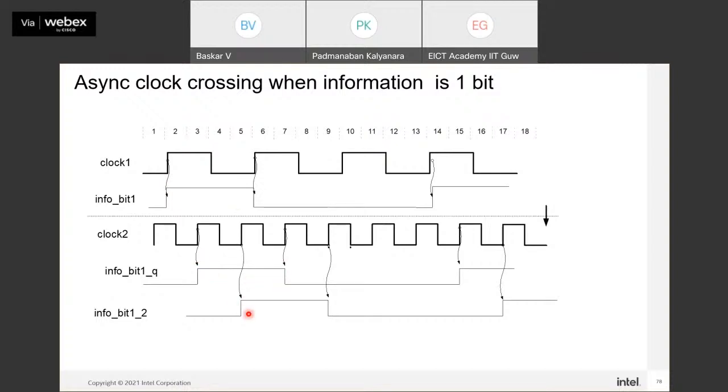It is still okay for the destination as long as the destination logic understands that it should treat this 2 cycle pulse as a single 1 cycle pulse, or it doesn't care whether the duration is 1 clock cycle or 2 cycles. All it cares about is only the edge, then it is fine.